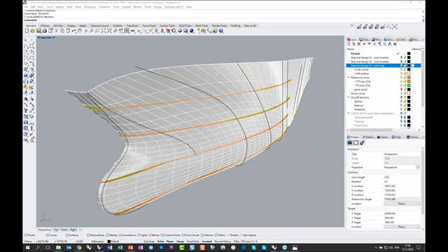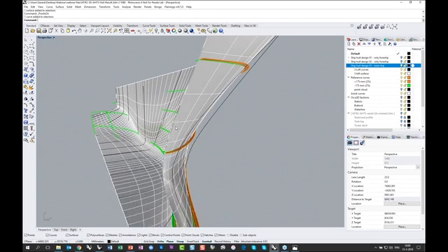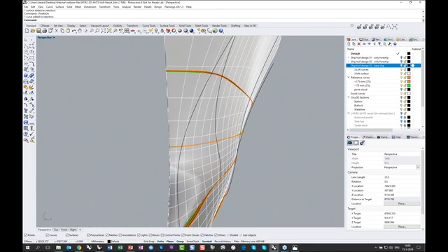Amitava asks, I'm interested to learn how to develop ship hull from a large number of points. Typically, these points are extracted from structural analysis models, such as an STL file. So yeah, somebody who has a lot of points. Yeah, again, when you have an STL file, which we call a mesh surface, then you need to create sections in that mesh surface and use the section curves to create reference ribs. So with reverse engineering, in our practice, you always use your input to create curves that you use to create reference ribs, the orange and the green ones, and then you start all over again with a new surface which you fit to that original input.